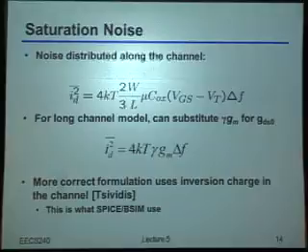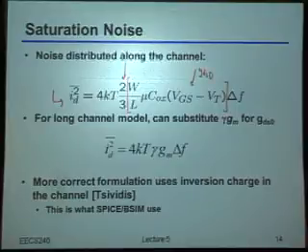If you do exactly that integration, you'll find that, nicely enough, you get a drain current noise density that becomes exactly the same as before, meaning 4 kT times GDS naught times delta F, but scaled by this so-called gamma factor, which, at least for a long channel device, turns out to be 2/3. So just to deconvolve this expression, this whole piece right there is just GDS naught. So really, this is exactly the same expression as before, just scaled by a factor of 2/3.